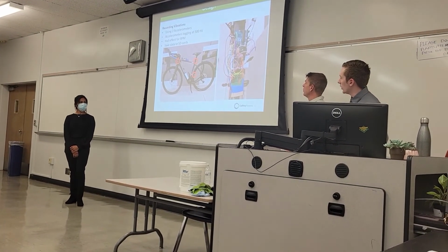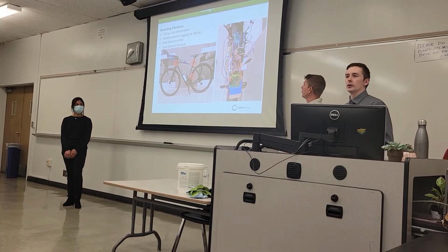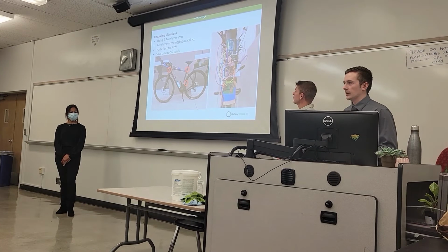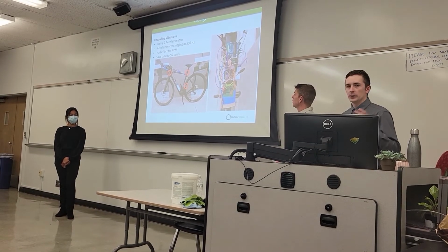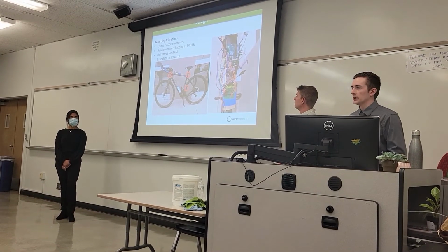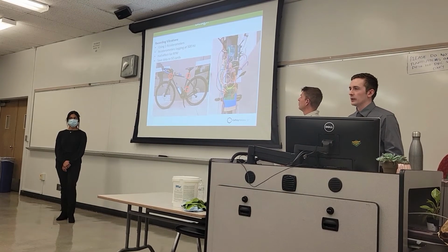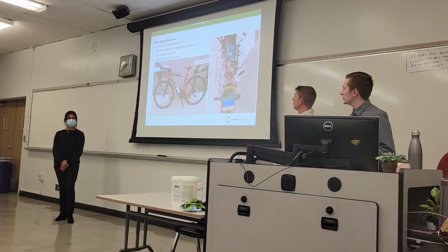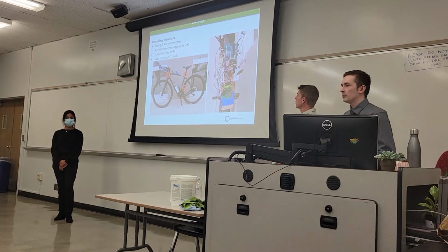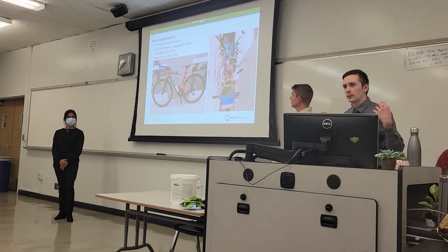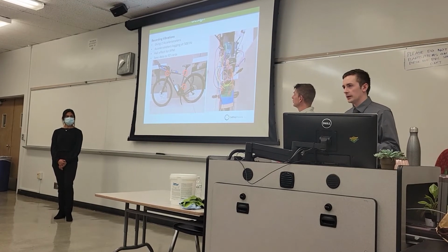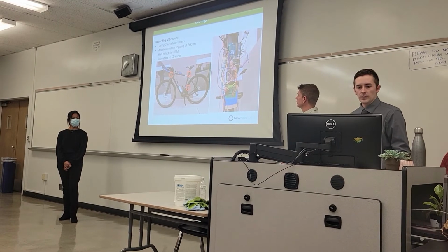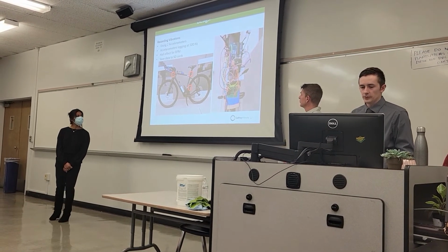Each accelerometer is logging at 500 hertz, which was quite a challenge to get working because Arduinos can only sample so fast, and they have such a small storage space that if you sample really quickly, you quickly run out of space, or you can't sample fast enough. So that was a real challenge to make work. We need to sample at such a quick rate because we're trying to measure vibrations, and to detect a quick spike in vibration, you have to sample really quickly. And then all the data is being saved to SD cards through the Arduino.